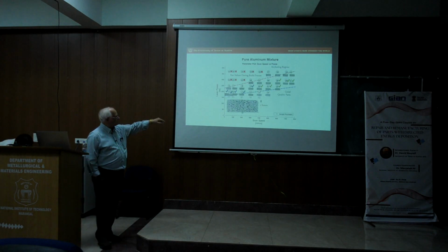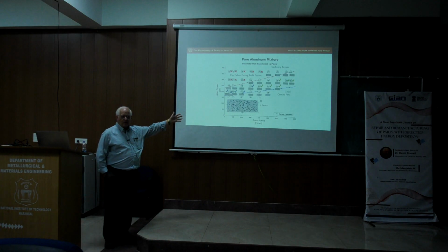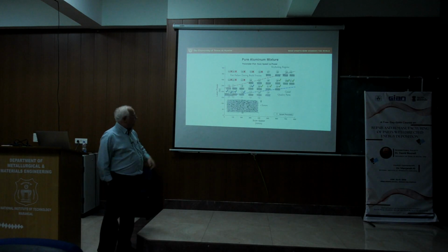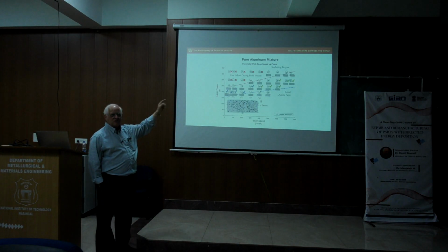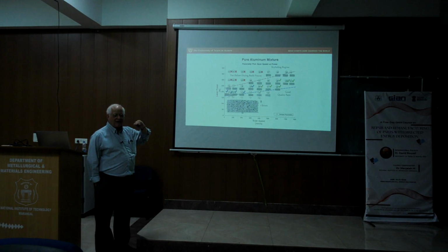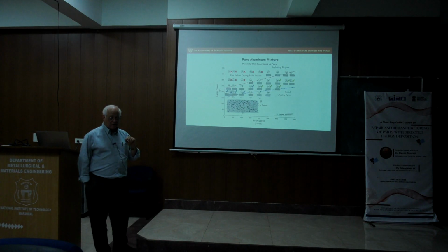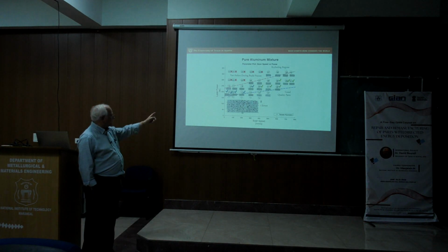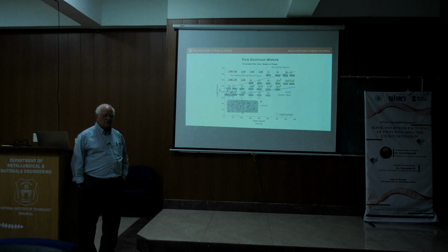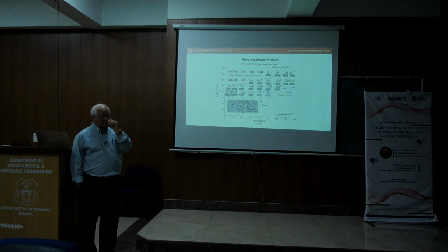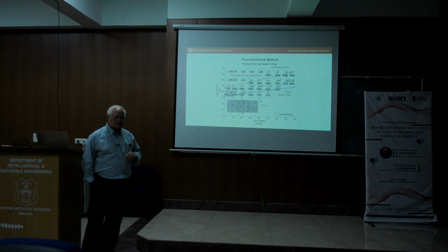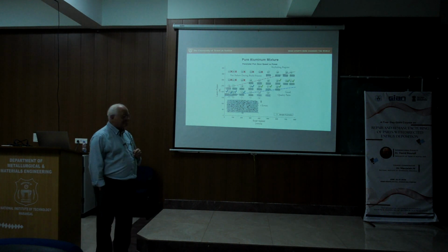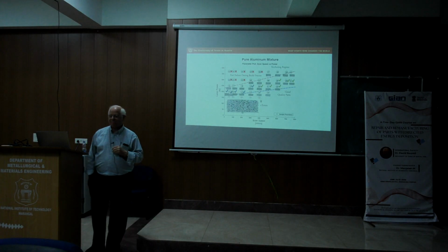In this case, we have to be a little careful: this is pure aluminum, not the aluminum-silicon alloy. But the aluminum-silicon will do the same thing. We can get these fusion errors, fusion porosity. Absolutely.